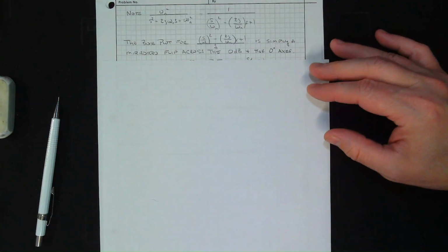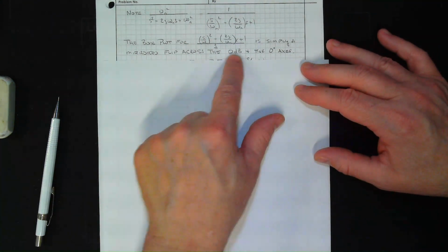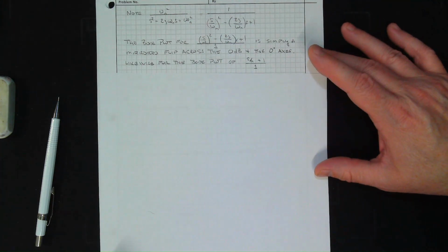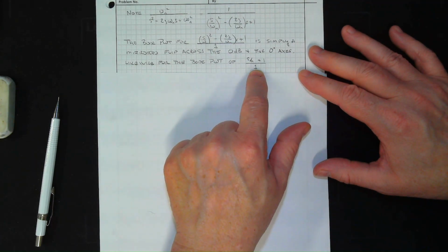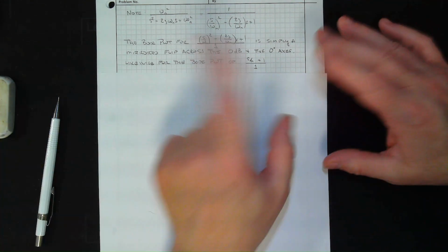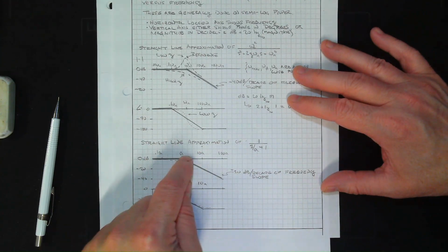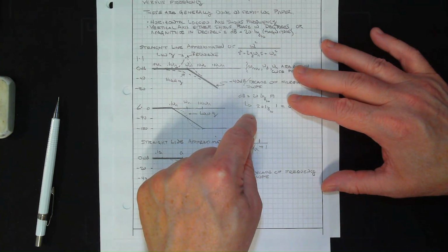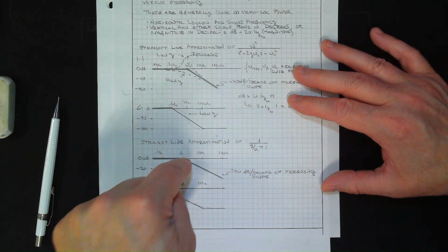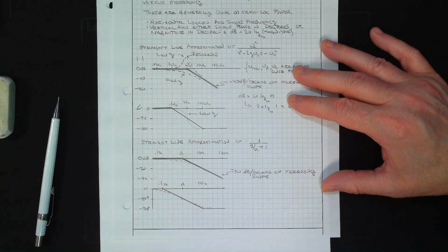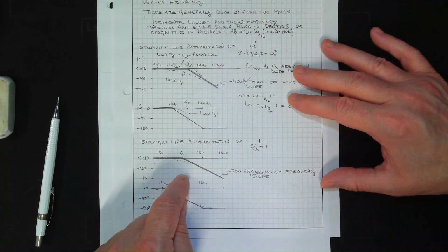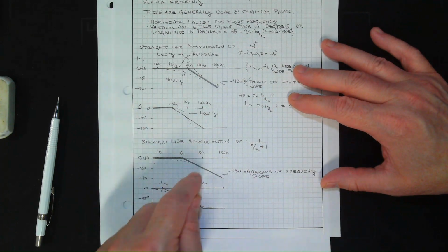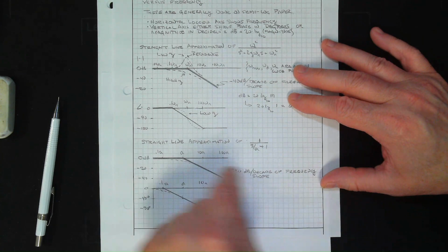So we've plotted it for poles. We can do the plot for zeros. Likewise, if you had a first order zero, s over a plus 1, no problem. It's just the same idea. For this plot, you get to a, you go up at 20 dB per decade. Here you went up at 40, here you go up at 20. Likewise, for the phase, you start at 0.1, you go up to 45 degrees at a, at 10a, whatever a is, you hit 90, level off.